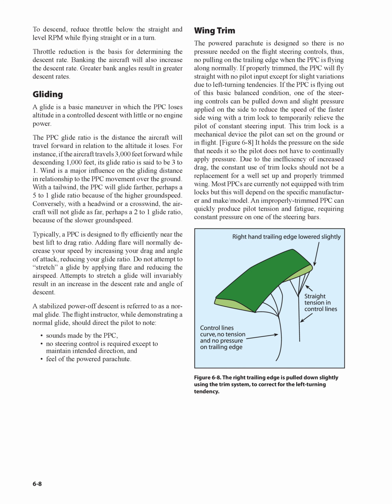Figure 6.8, it holds the pressure on the side that needs it so the pilot does not have to continually apply pressure. Due to the inefficiency of increased drag, the constant use of trim locks should not be a replacement for a well set up and properly trimmed wing. Most PPCs are currently not equipped with trim locks, but this will depend on the specific manufacturer and make/model. An improperly trimmed PPC can quickly produce pilot tension and fatigue, requiring constant pressure on one of the steering bars.